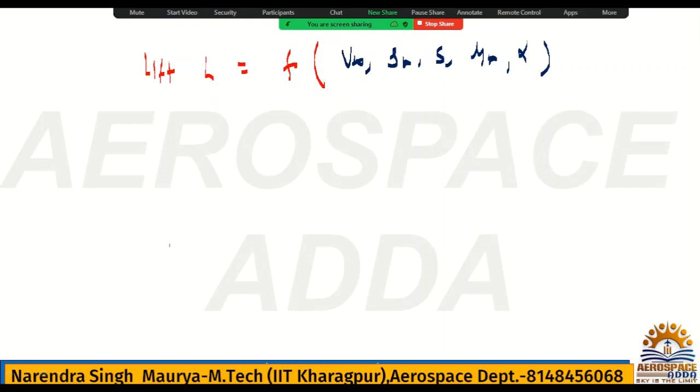So now if you ask what is the lift, basically there are two methods to calculate lift. One is by dimensional analysis, which is very simple. You all have done dimensional analysis in fluid mechanics, and there you had calculated lift force. If you calculate that, then what you may get is half rho V infinity square S into that coefficient which is called lift coefficient. This was the value. See, lift is a function of V infinity, so V infinity came here, lift is a function of density which is altitude, so density also came here, S which is the area of the wing, so S also came. You are calculating lift, so that coefficient will be coming, which is called lift coefficient.